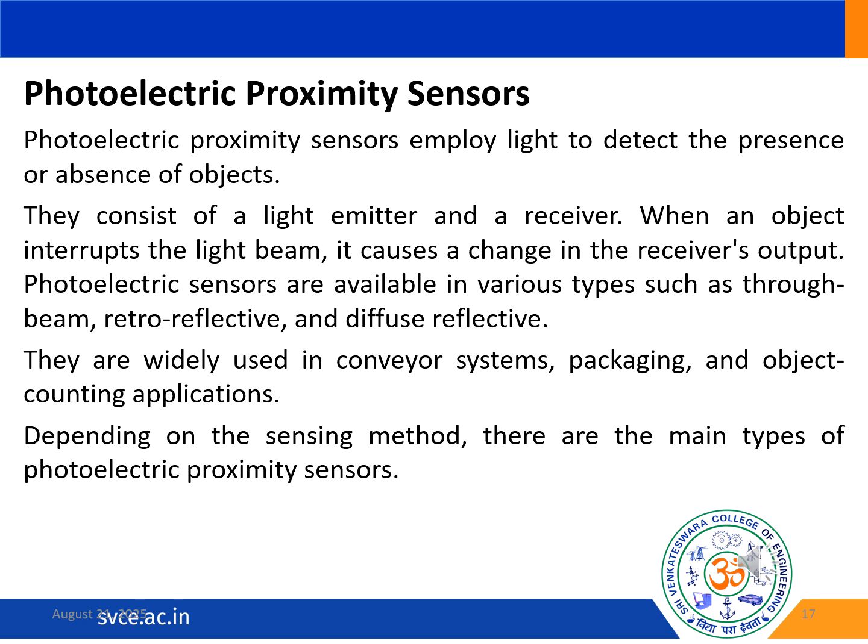An emitter delivers a beam of light directly towards the receiver, so this beam identifies the presence when an object breaks it. This kind of system necessitates the use of both an emitter and a separate detector, which makes the installation and wiring process more difficult.